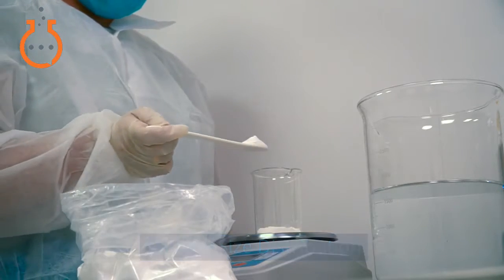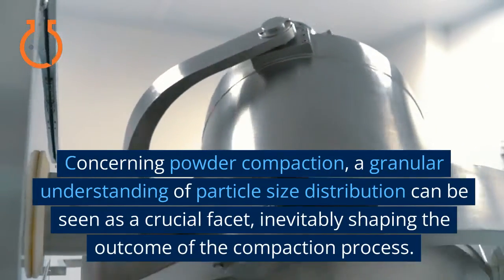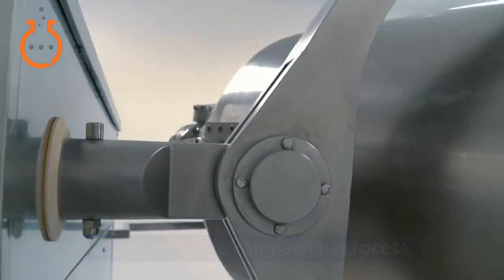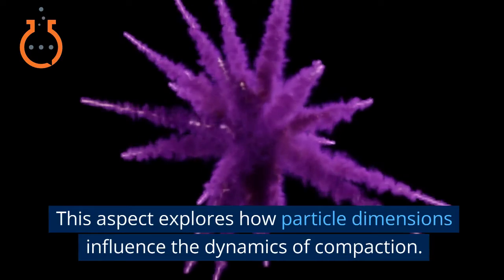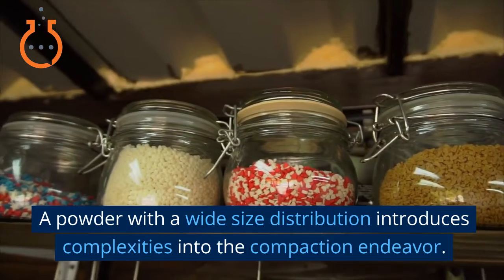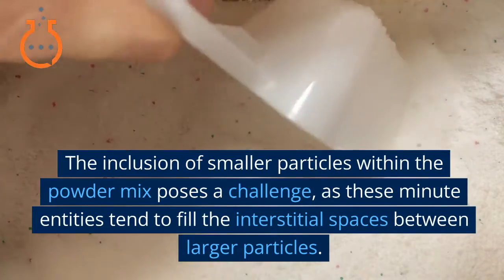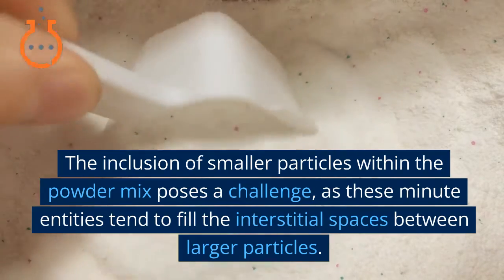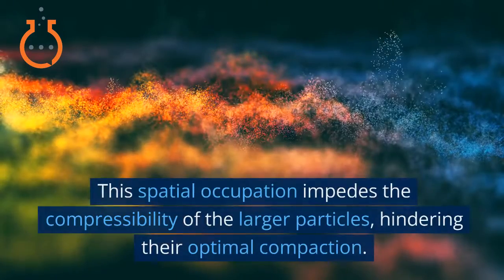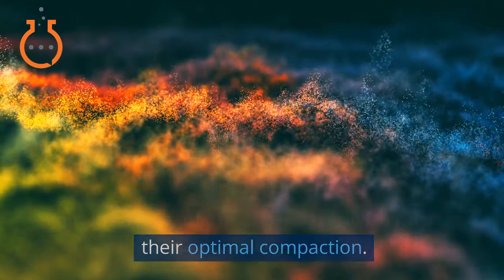Particle size distribution. Concerning powder compaction, a granular understanding of particle size distribution can be seen as a crucial facet, inevitably shaping the outcome of the compaction process. This aspect explores how particle dimensions influence the dynamics of compaction. A powder with a wide size distribution introduces complexities into the compaction endeavor. The inclusion of smaller particles within the powder mix poses a challenge, as these minute entities tend to fill the interstitial spaces between larger particles. This spatial occupation impedes the compressibility of the larger particles, hindering their optimal compaction.